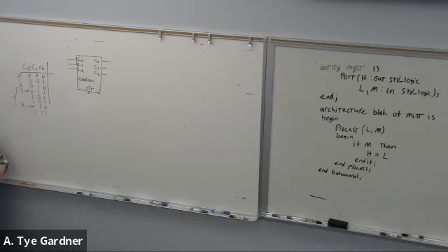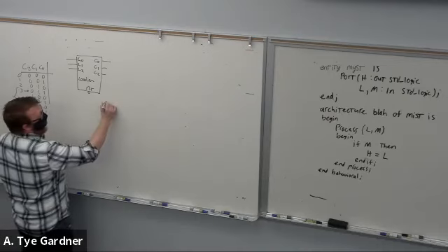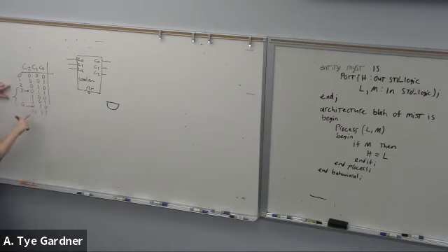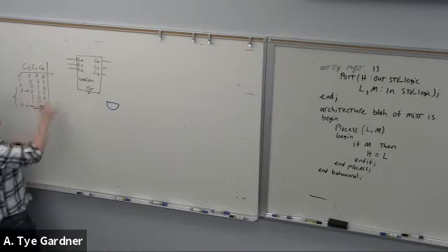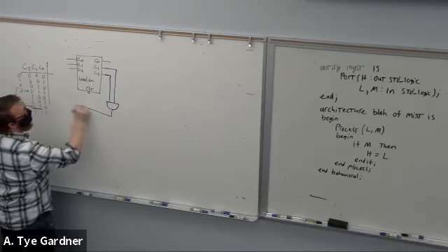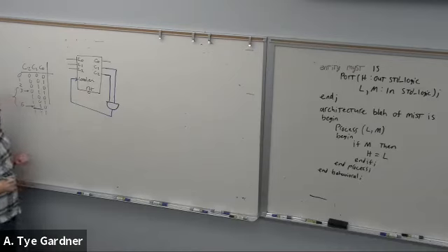Well, there's two ways I could ask it. I could just ask the way I did, which is simply draw me a circuit that counts from 3 to 6. Or I could say, draw me the minimum circuit that counts 3 to 6, right? And so the minimum circuit is just taking advantage of the fact that we recognize that the first time that we see 1, 1 is when we reset. So if all we do is take C2 and C1, plug that back into this load enable.